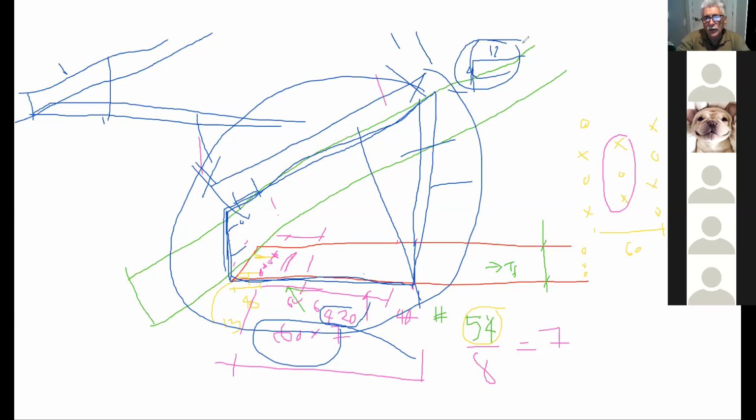This is one piece of information here, and this is the other piece of information. So some people believe that you give the minimum amount of information so that the guy calculates the rest, so that you can minimize the errors. That used to be the old days. Now, in the new days with AutoCAD, if you draw everything accurately, AutoCAD is going to accurately give him whatever he needs. So I'm from the school of thought that the more information you give, as long as it's correct, the less of a chance there is going to be a mistake down the road.